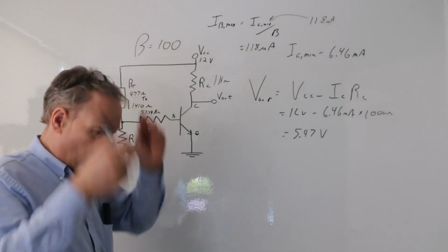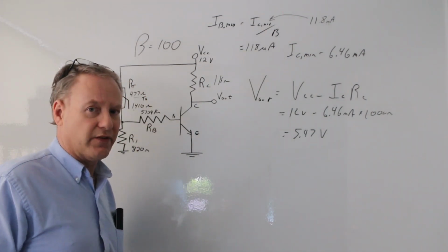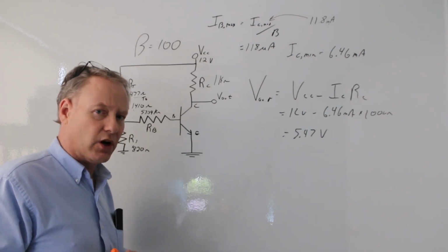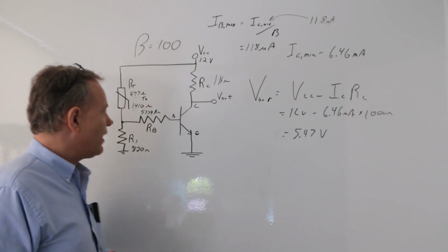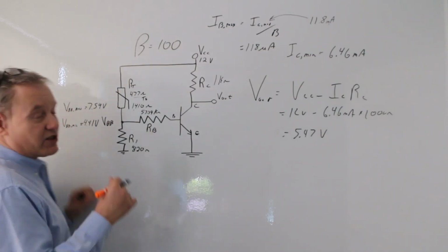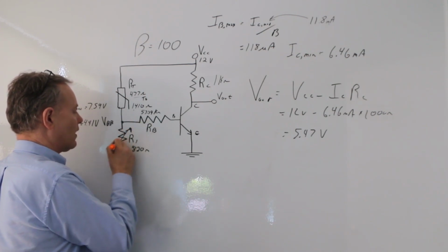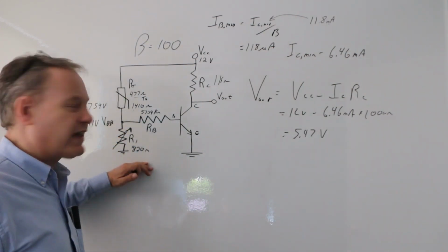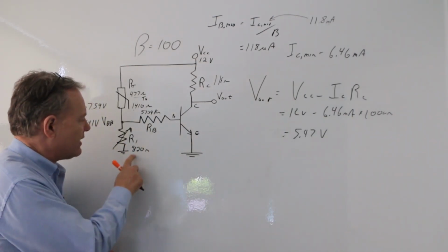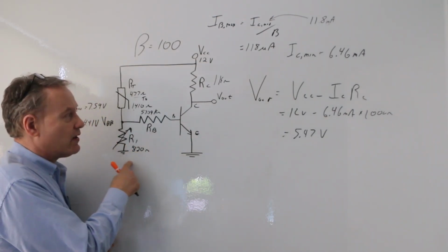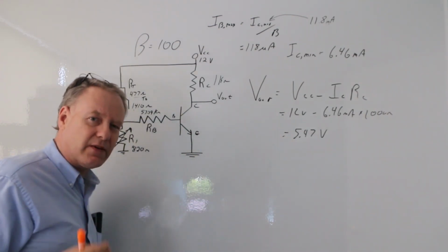Now, essentially what's going on is that an Arduino doesn't like anything more than 5 volts. Doesn't like that. So you can tweak this a bunch of different ways. One is, and this is really the ultimate way to do it, you can put a pot in there. Get a 1K pot and put it in there. And you can adjust that. You can see that if I made this a lower value, this would come down just a little bit and you could tweak it so it just came to 5.